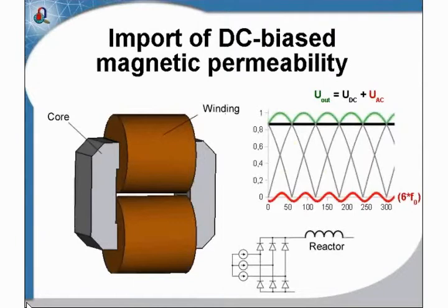This is the filter reactor. The purpose of this device is to smooth the current fluctuations. From thyristor power source, I get DC voltage with some fluctuations. I would like to smooth fluctuations. I place the reactor at the output and hope that its inductance will lessen the fluctuations level.